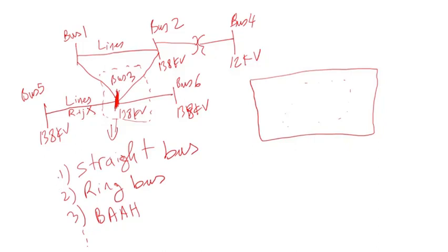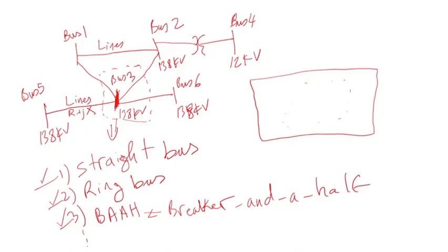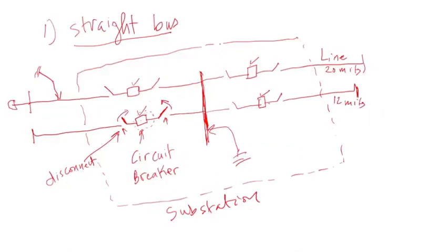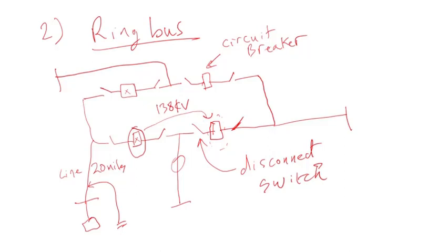Like I was saying, here's one way you can represent a bus: a straight bus, a ring bus, a breaker and a half. I showed a straight bus representation and a ring bus. Now I'll cover the breaker and a half.